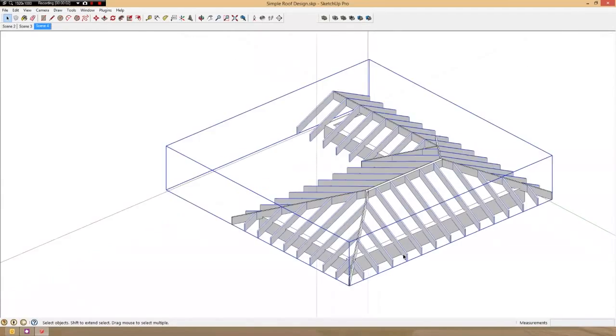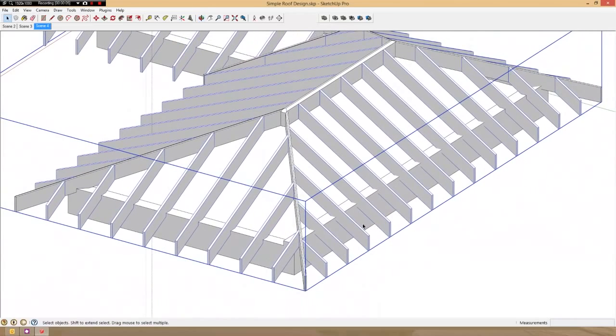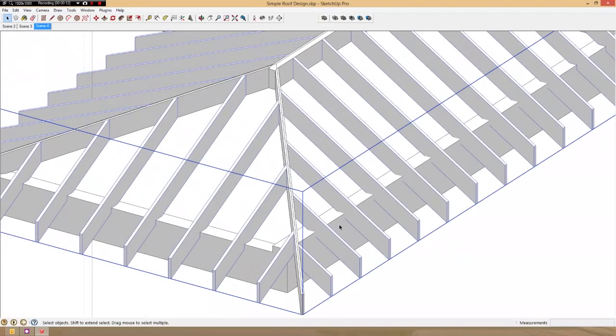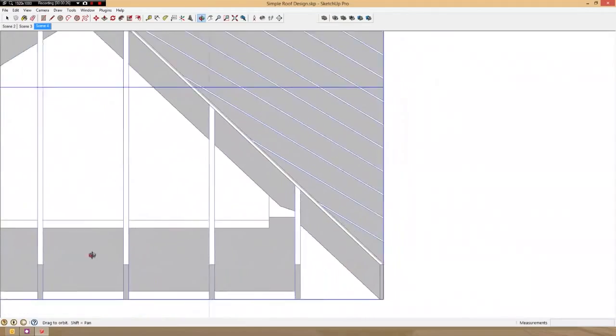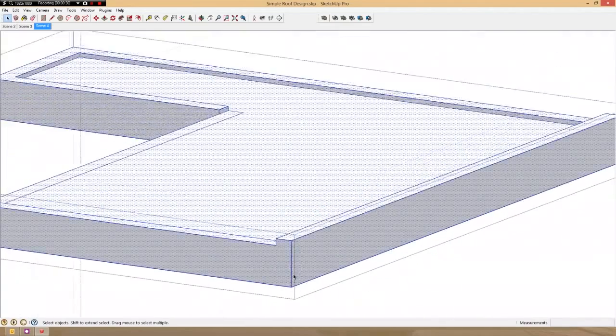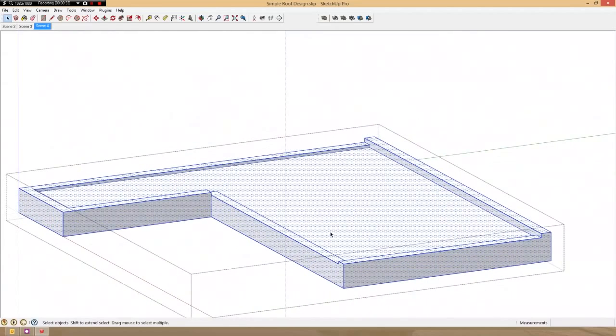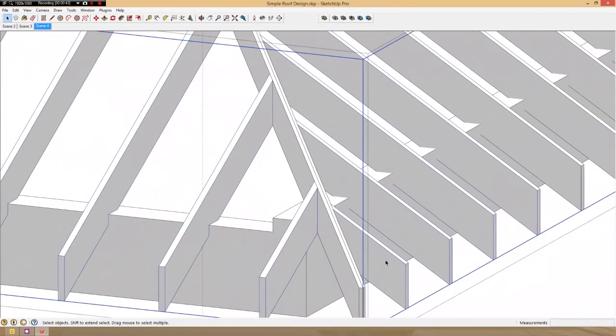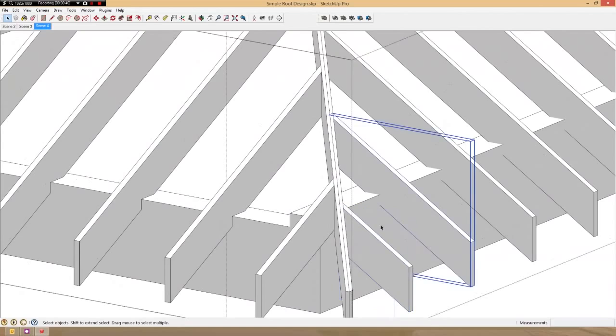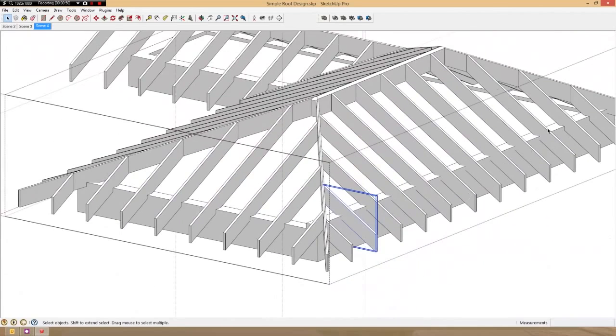Let's cut our seat cuts and wrap this tutorial up. Because we have an irregular pitch roof, the wall heights have to vary such that we get seat cuts with an 8-inch height above plate. In this case, that meant 4 different heights of the plates. I've left this section undone, so we'll go ahead and go through it.